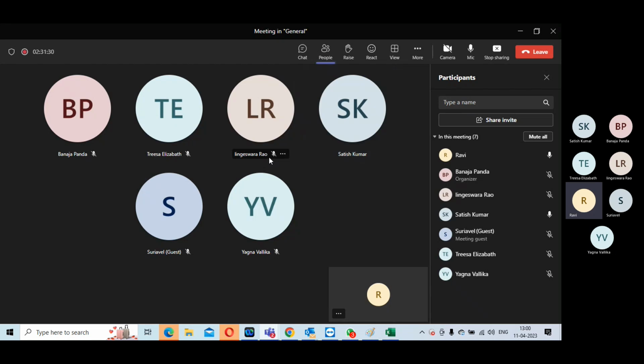Before you run the DRC check, add post fills, then run the DRC check. Then it will give you base DRC clean, or it will tell you all the issues. Macro to macro, if DRCs are there, there is no point in proceeding beyond that because it will further screw up all your placement. Do a good floor plan, do it properly and neatly, and get it base DRC clean.